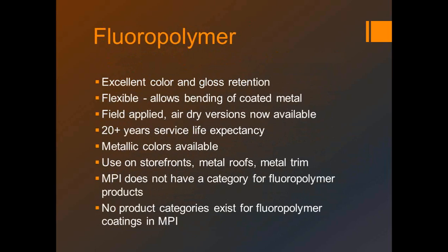If you had originally a painted storefront and then you come back, we need to do some alcohol checks or try to figure out what kind of coating is on that surface before we make a recommendation. The last thing you want to do is put a really good system over something that will lift. Yeah, exactly, a lesser system underneath it that they haven't bonded to. So that's one of the aspects of looking at things.